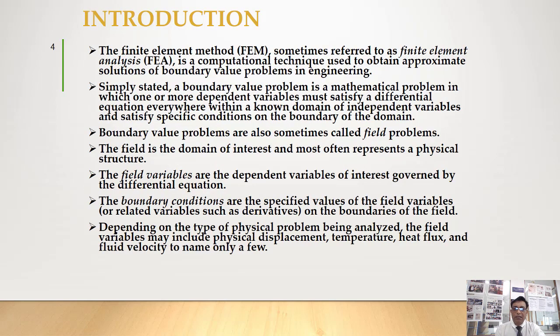So the finite element method, sometimes referred to as finite element analysis (FEA), is a computational technique used to obtain approximate solutions of boundary value problems in engineering. It is not an exact method; it is an approximate method. Simply stated, a boundary value problem is a mathematical problem in which one or more dependent variables must satisfy the differential equation everywhere within the known domain of independent variables and satisfy specific conditions on the boundary.